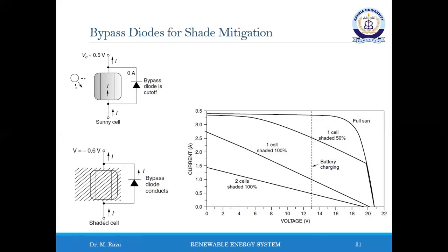The reduction in the charging current for even a modest amount of shading is severe, with just one cell shaded out of 36 in the module. The power delivered to the battery is decreased by about two-thirds. A solar cell in full sun operating in its normal range contributes about 0.5 volt to the voltage output of the module. But in the equivalent circuit, a shaded cell experiences a drop as current is diverted through the parallel and series resistance. This drop can be considerable.